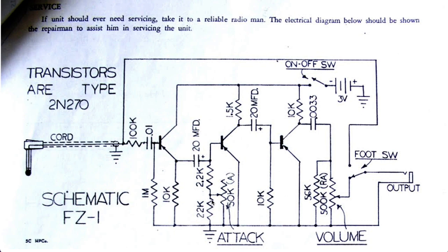And let's see what else is interesting happening here. Notice that the bias resistor connecting the base to ground for the second stage involves a potentiometer hooked as a variable resistor. And this is called a TAC. So this lets the user adjust the biasing. Now, we've been doing linear analysis in this class. Of course, the whole point of a fuzz pedal is that you're driving it to operate in a nonlinear mode of operation, and that's how you get the cool, weird distortion. But starting out with a linear analysis gives you an initial insight on how the circuit is working.